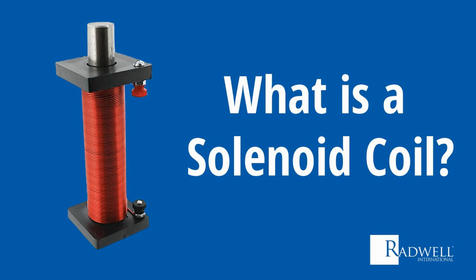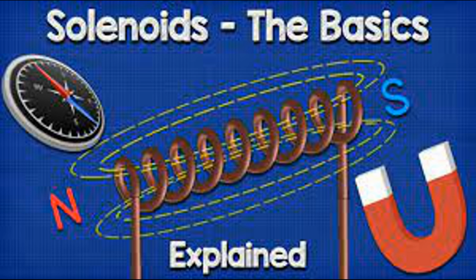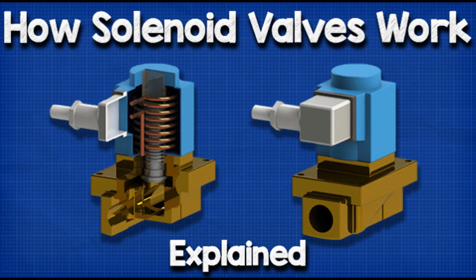4. Consumer electronics and appliances. Printers and copiers. Solenoids are used in printers to control the movement of paper, ink heads, and trays, ensuring precise operation. Vending machines. Solenoids control the dispensing of products like snacks, beverages, or change by actuating levers that release items. Washing machines. Solenoid valves regulate the flow of water into washing machines, controlling the wash cycle and water levels. Dishwashers. Solenoid valves control the water flow in dishwashers, determining when to fill and drain water.